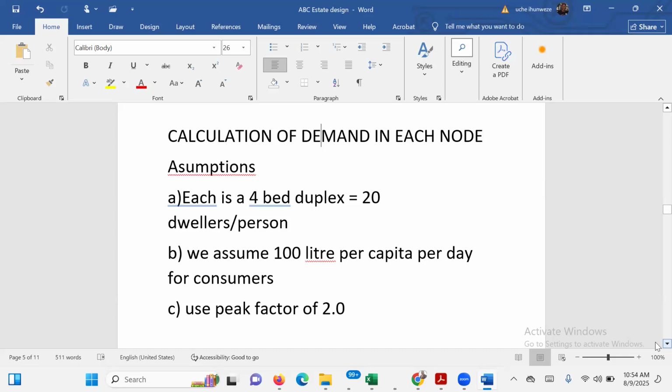Your final population projection must take into account the lifespan of your proposed water system. If I want the lifespan to be 50 years, in other words, in 50 years' time there won't be any new design, then I need to use the population at 50 years, as well as development and other factors that we have discussed, at 50.